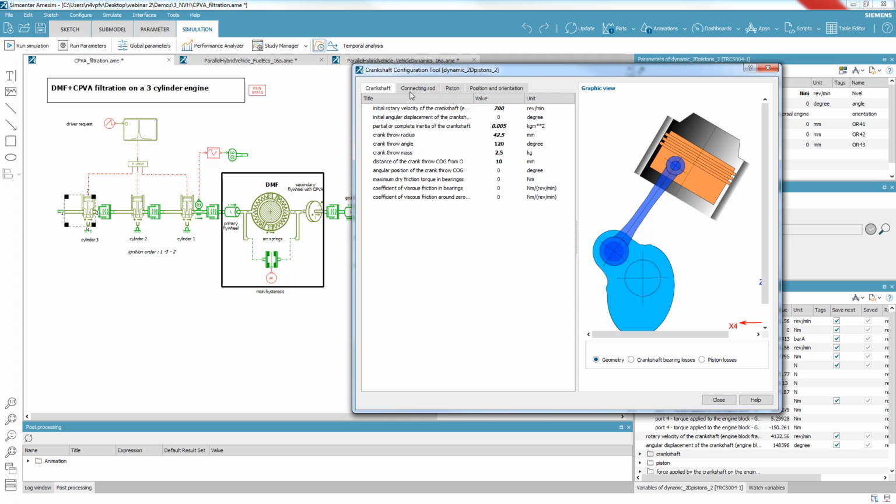but also the rotating masses in the crankshaft, and the piston at the level of the crankshaft itself, the connecting rod, the piston. And also torque oscillation will be generated by the torsional behavior of the crankshaft. You can see here an app which is dedicated to the cylinder and crankshaft submodel, and that helps users to define parameters easily and faster.